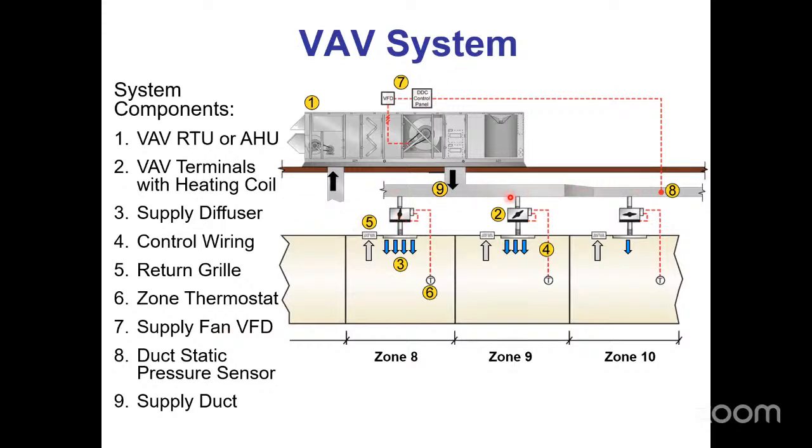It's going into these individual dampers. They each have a thermostat saying, I'd like more or less cooling. And if that's a perimeter zone and it gets cooler, it can engage its local heater, duct heater, hydronic coil, baseboard, etc. I'll have diffusers coming off of all of those VAV boxes, probably more than one. That'll go to 2, 3, 4 diffusers serving that particular area of the building. I'll have all these diffusers on there.